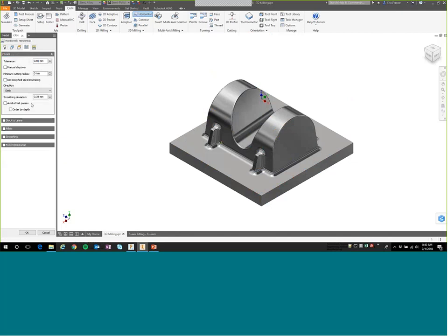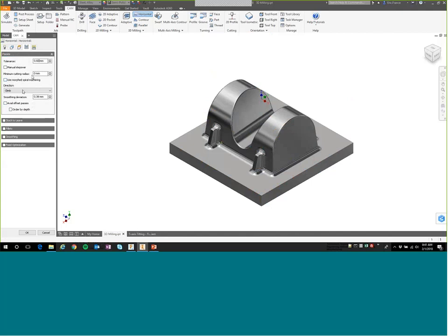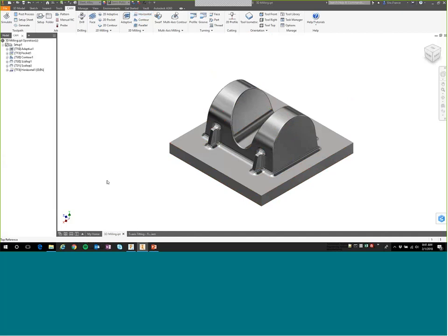and be able to make the adjustments that we need to. So we'll adjust our tolerance, and let's see, and our smoothing deviation. We'll go ahead and set that to 1 millimeter for this one. And again, we want to pretty much finish off that bottom, so we're not going to leave any stock on that. And we'll see what this comes up with. All right, so you can see that it's identified the toolpaths around that horizontal area, which is good for a cleanup there.